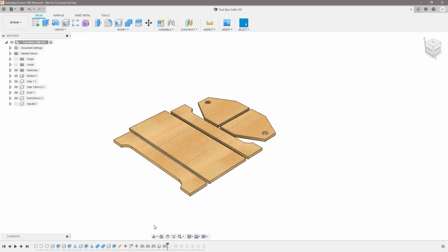And just remember that you can actually clean some of these things up. These commands here, the move, the align, and the move, are actually kind of overwritten later on by these joints. So there is actually no sense of keeping these in here.